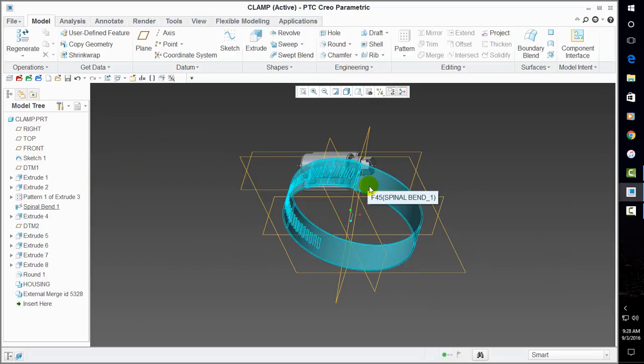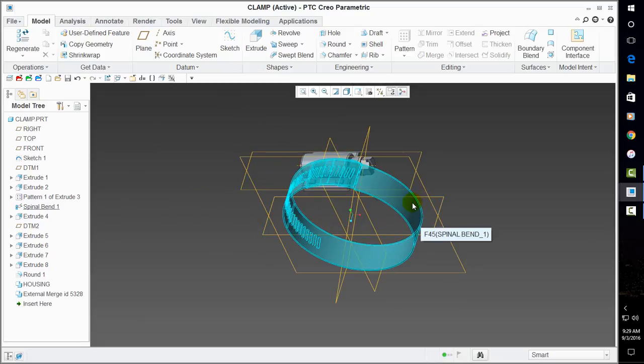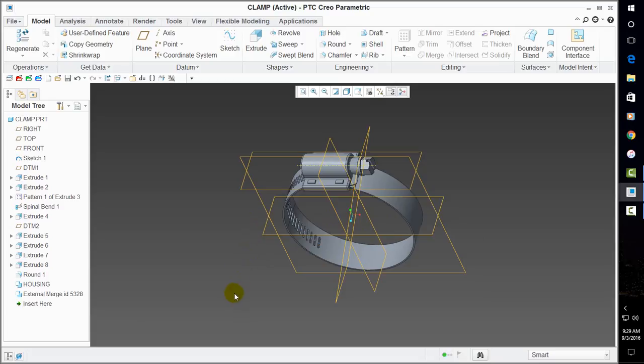And the reason why we're going to do that, if somebody edits in the next higher level, we're going to make hose diameter just a sketch basically. And that's what's going to be flexible. And what I'm going to do is check, and if somebody puts that number outside of the range of the clamp, I'm going to reset it. I can't make it the dimension directly, because every time you change a dimension, Creo 3 regenerates the thing automatically. So it will fail. So I'm not going to do that.